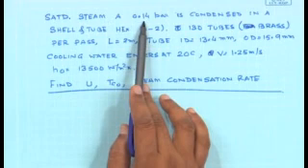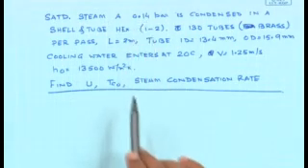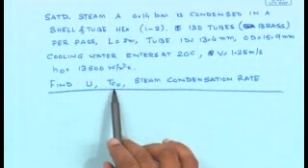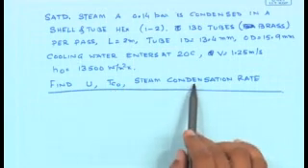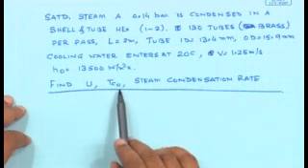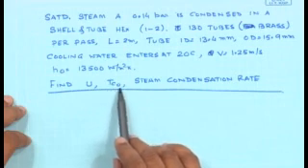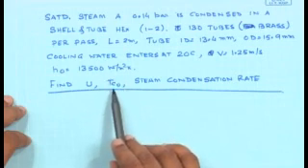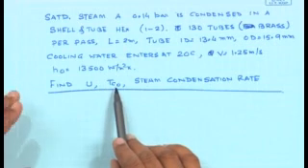However, one of the outlet temperatures is unknown and the steam condensation rate is also unknown. So there is no way simple LMTD would give us the temperature of the cooling water. It would require an iterative procedure.